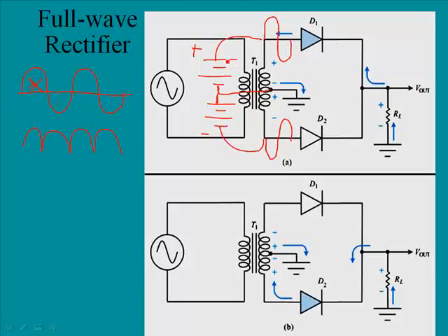And if we look at the polarities of our battery, it will make the current quite easy to understand. Here, the upper diode is going to be the conducting diode, and remember that our polarity needs to be negative to positive across the diode in order for it to conduct from the cathode to anode. You notice you have the large positive signal here, which would indicate this is probably going to be conducting. And on the bottom side, you have the large negative, which probably tells us this is going to be cut off. But let's look at it in terms of the battery.